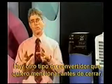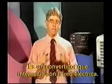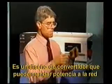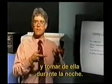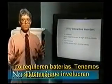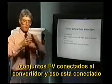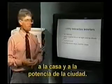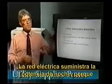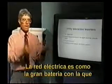There's another type of inverter that I want to mention before I close. That's a utility interactive type of inverter. A design of an inverter that can send power out to the utility and draw from the utility at night. Typically, utility interactive inverters involve no batteries. We have systems that involve photovoltaic arrays connected to the inverter, then that's connected to the house and to the city power. No batteries, no charge regulators, and so on. The utility supplies the power at night because the modules don't work at all. The utility is like the big battery that you can rely on anytime.